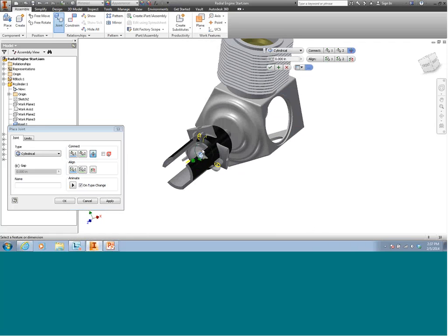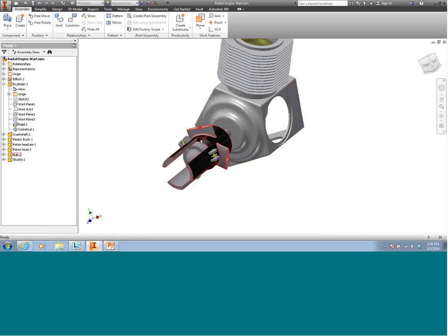You can see it moves into position. So I've used the cylindrical constraint, and you can see that this allows me to move it in and out. So I've got interference happening here, as well as rotated, which also gives me interference. So now I've got to clear that up to make sure that I'm constraining that component properly.